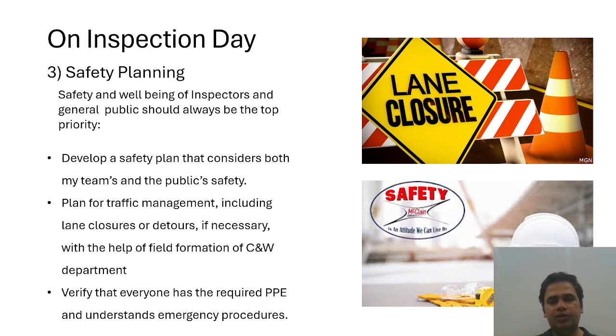And similarly, when you will be inspecting the bridge from the top, you should have a proper arrangement for the traffic diversion, for the lane closure, so that no inspector is hurt in any way, and the smooth running of the traffic is also ensured.